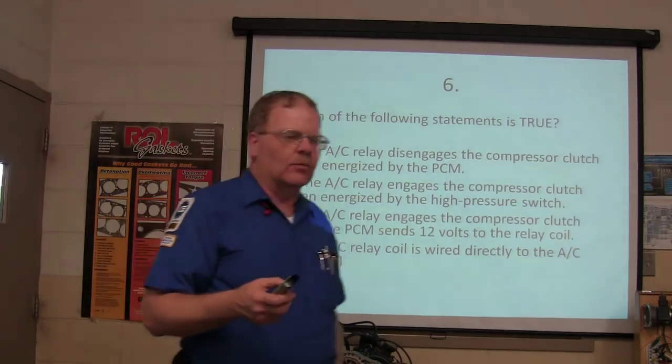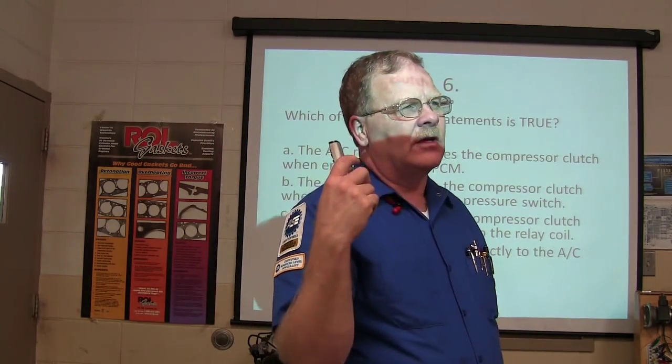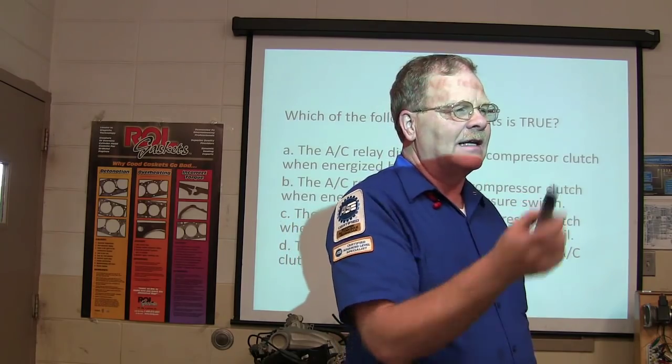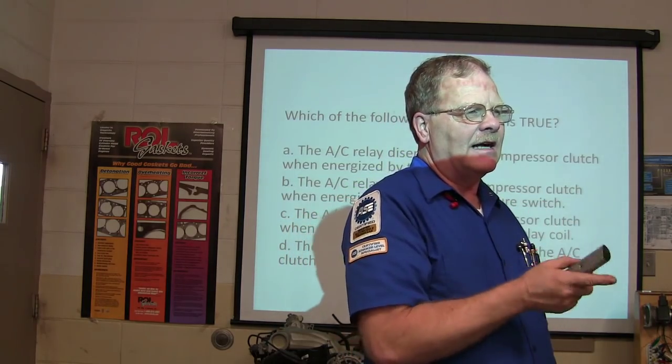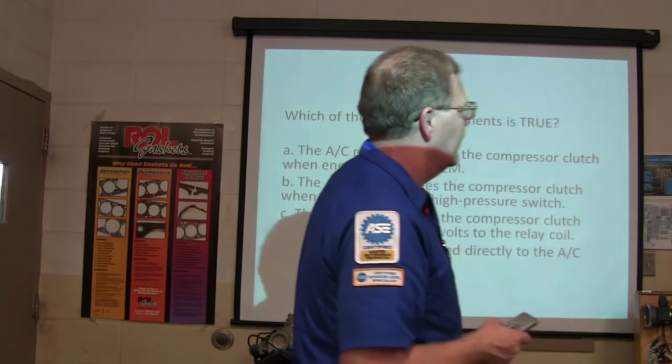No, on this particular one and on most of them, the older Fords used to energize the relay to kill the compressor, but now anytime it energizes it, it's going to throw the compressor in.